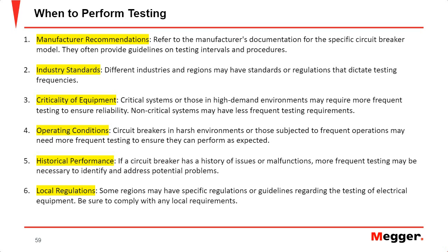You can take a look at industry standards. So the standards we had previously and see, okay, hey, what do they recommend as far as how often I should test breakers? Typically, you'll see every 3 to 5 years as a requirement. If it's more critical, you'll say every 2 years, maybe every year. A lot of insurance companies will say, okay, hey, for ground fault testing, we want to have testing done every year, and we want to have documentation of that. And again, the reason for that is because a lot of faults that you'll see, typically ground fault will be the first fault that occurs before any other faults occur.